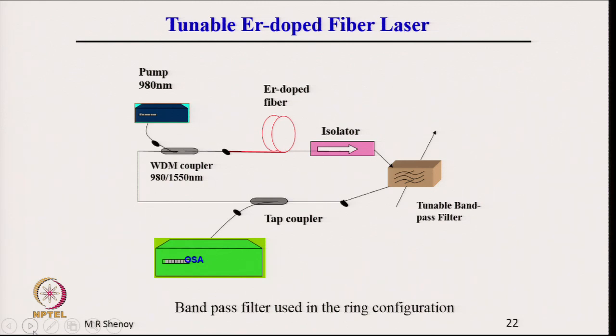Okay. Last point is tunable erbium doped fiber laser. So, as we discussed, if you take an erbium doped fiber, then it has an absorption cross section something like this. We had discussed this earlier when I discussed EDFA. I had given the graph, and an emission cross section which varies something like this. So, there is a range of wavelengths. So, what I have plotted is sigma E and sigma A, and this is wavelength lambda.